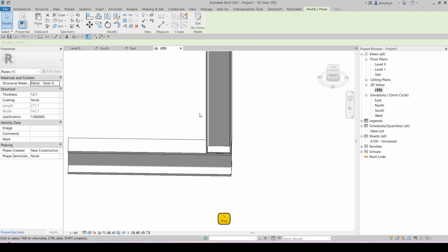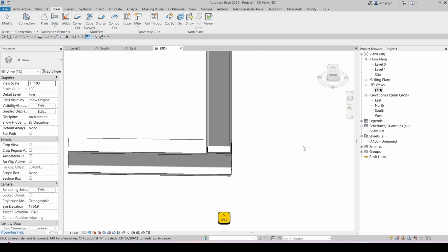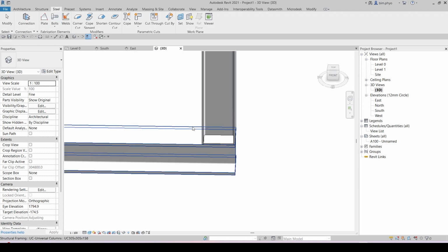So you need a bolt nut, so you need to look for it here. That's T here. So you can choose what type of bolt nut you want. I'm going to choose a bolt, so I will click over this. This is an option. After you click this, you have to select where exactly you want it. I'll give you a better idea.